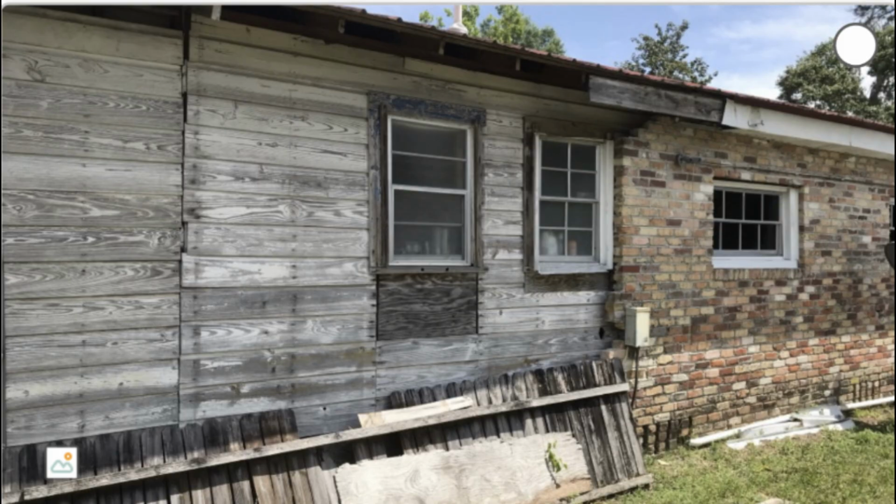Here's another home we inspected that we thought was kind of interesting. With this current home, you can see we've got multiple types of construction. We've got a brick part of the foundation. We've got an addition that's just wood. It's older, kind of weathered wood. This presents a whole other list of issues. You can also see up at the top, the fascia board is exposed to the elements. So you can see a lot of issues with this.